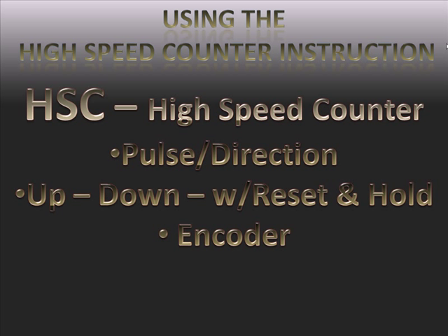If an input terminal changes state several times while the logic is being scanned and executed, in other words, from on to off and then from off back to on, the processor finds the same state at that input when it goes out and looks again that it found on the previous scan. Hence, there's no transition for the rung containing the count up or count down instruction, and the count is lost. So the high-speed counter is an actual electronic device permanently connected to specific input terminals. And when activated, it counts totally independent of the processor scan time.